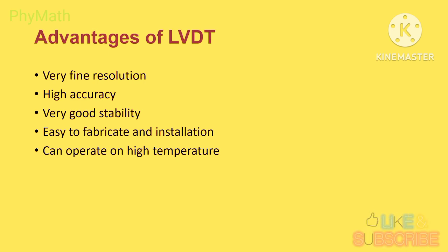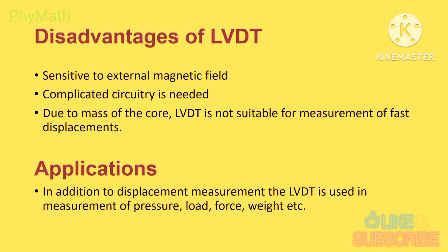Now, what are the different advantages of LVDT? First, very fine resolution. Second, high accuracy. Third, very good stability. Next, it is easy to fabricate and install. Then next, it can operate at high temperature. These are the advantages of LVDT.